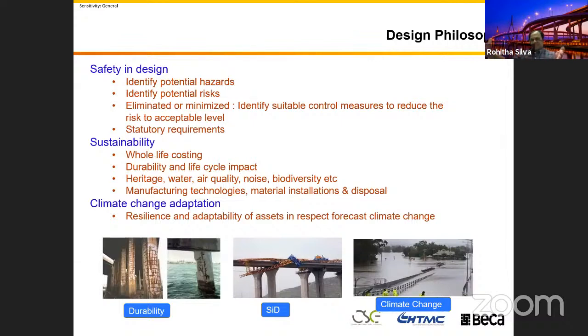You minimize the maintenance, but sometimes you have to put more money in upfront. You have to make sure you look after all the quality control. You can have designers come up with a really good quality bridge design, everything is in there, but if you build it in a very bad way, there's no point having that design. Let's say you design right and you build right, but you don't maintain it. For example, I explained last time, in session 2, the bridge bearing has a design life of 35 years.